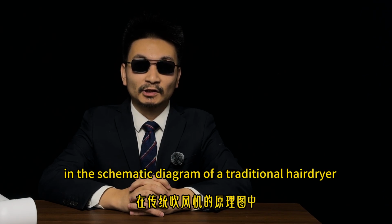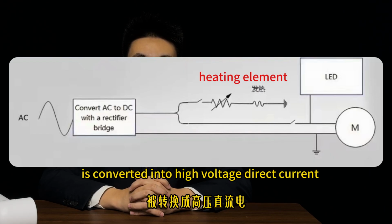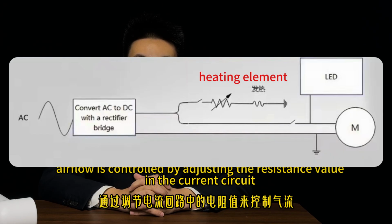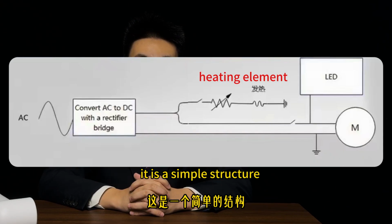In the schematic diagram of a traditional hair dryer, alternating current is converted into high-voltage direct current by a rectifier bridge, which is then directly connected to the DC motor. Airflow is controlled by adjusting the resistance value in the circuit or using on-off switching. It is a simple structure.